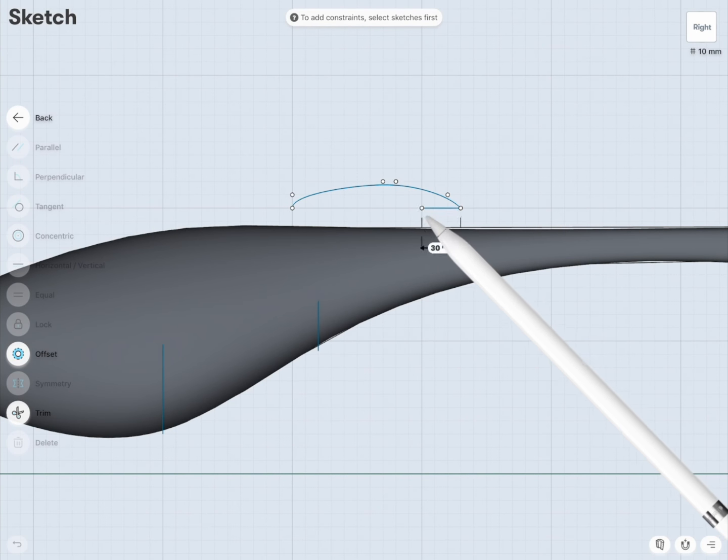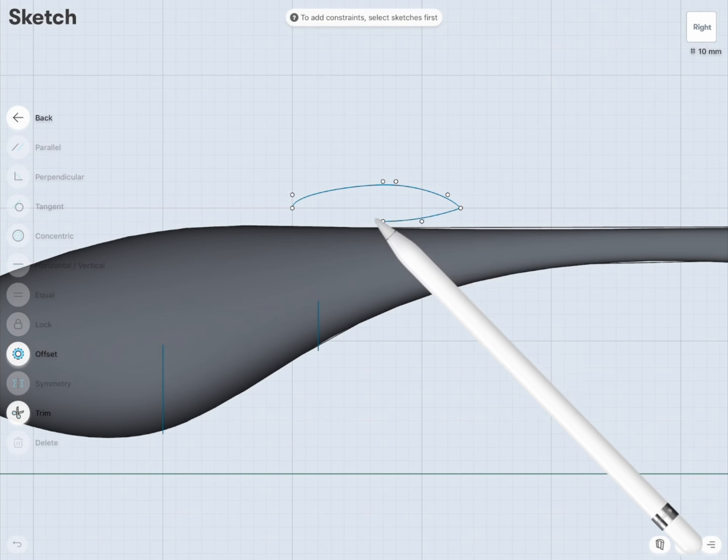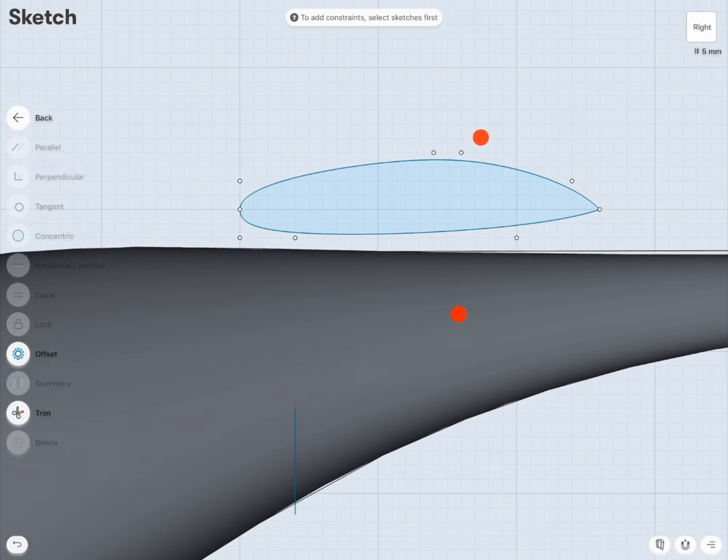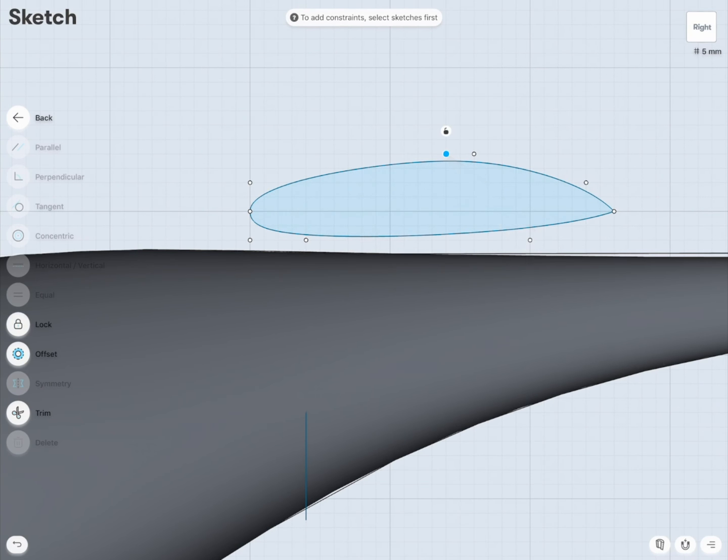Sketch a spline of this shape, but remember, the second and the first before last points must be exactly on the same line as the first and last points and perpendicular to the mirror axis. This trick will make the front of the wings smooth and the back of them more sharp, so don't worry about those points here.